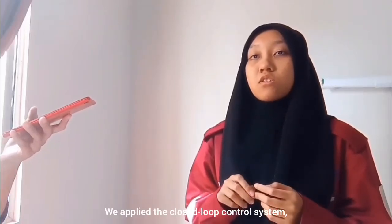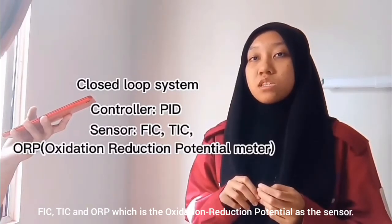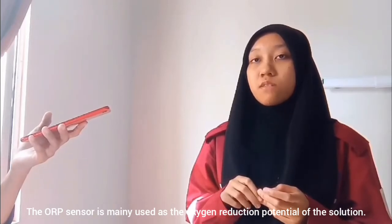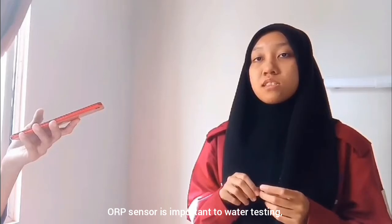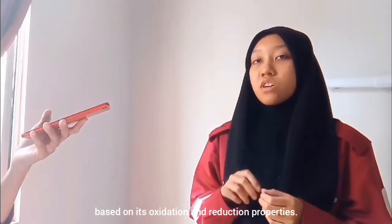We applied the closed-loop control system with PID as the controller, FIC, TIC, and ORP, which is the oxidation reduction potential, as the sensor. The ORP sensor is mainly used to measure the oxidation reduction potential of the solution. The ORP sensor is important to water testing because it indicates how sanitized the water is based on its oxidation and reduction properties.